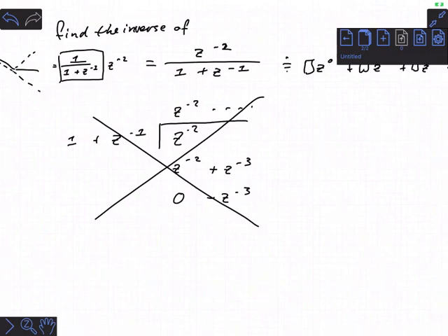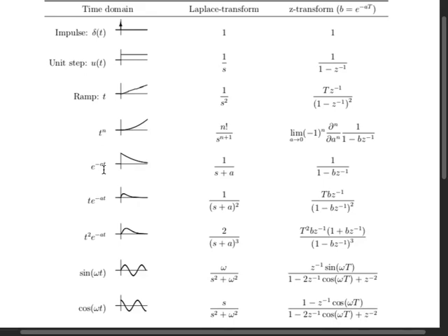And you only need to know how to do that through series expansion or through the built-in routines in some of the libraries that I'm also going to show you in the notebook. But the most important thing is that people think you can actually go back and forth between these tables without loss, which is 100% not true. And so you should interpret this table differently. You should really just think of this as the Z transform of the sampled version of that thing. And remember that little line that says you can only go one way.